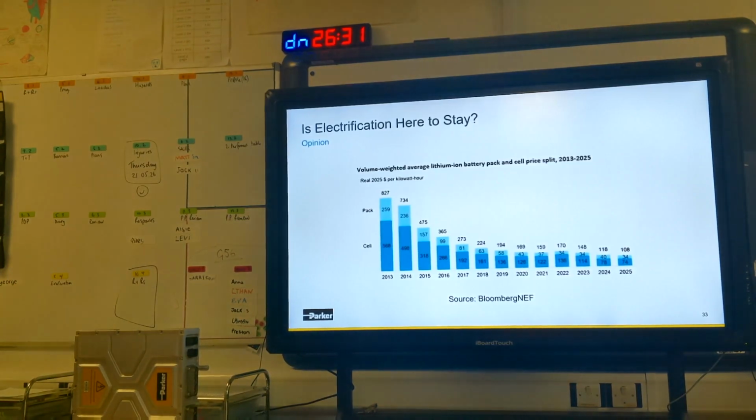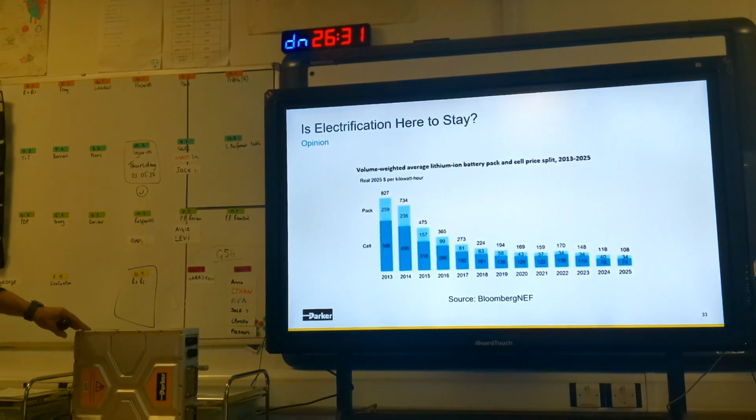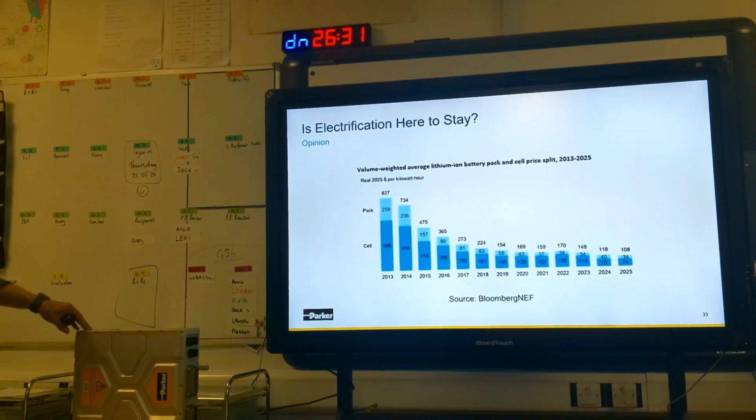And you also need switching power electronics with high switching frequency power devices. And you're really starting to see that now. I mean, we used insulated gate bipolar transistors in this. We're now getting to the point, because of the automotive sector, where there is sufficient silicon carbide FETs that we can move to those economically.